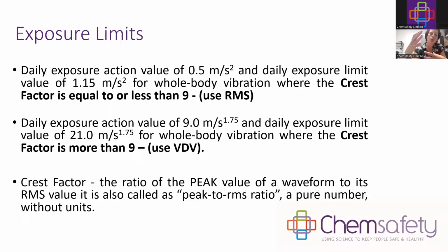So with the vibration meter, to access the crest factor, the VDV, and the RMS, they do have different settings afterwards when evaluating your data. So when you see that your crest factor is less than 9, then you'll use your RMS set of data, and if your crest factor is more than 9, you'll use your VDV set of data.